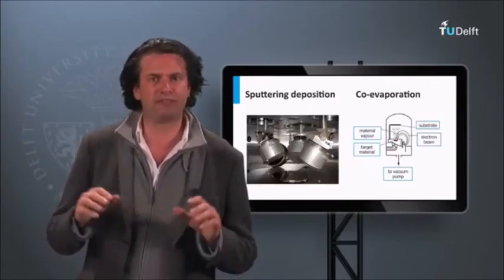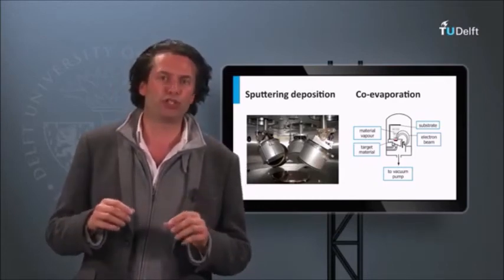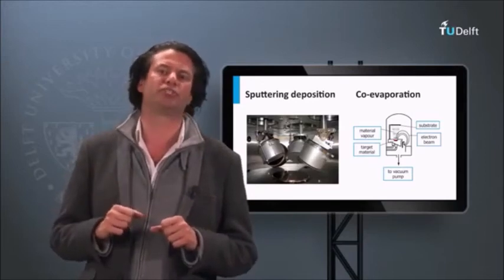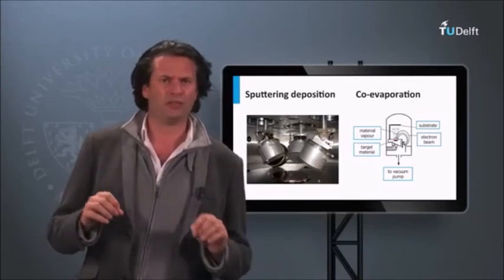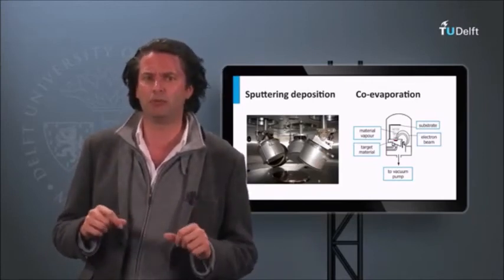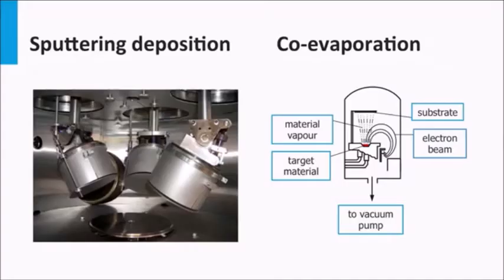In contrast to the thin film silicon technology discussed earlier, CIGS films can be deposited using a variety of deposition technologies. As many of these activities are developed within companies, not much detailed information is available on many of these processing techniques. One of the processing techniques is co-evaporation or co-sputtering under vacuum conditions. Using various targets of copper, gallium and indium, the precursors in various steps are co-evaporated onto a substrate.